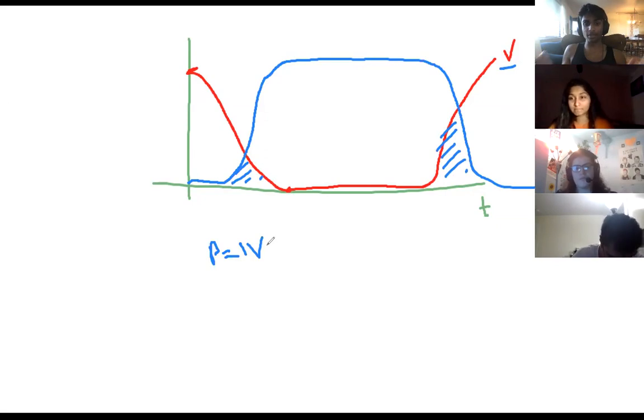So there's never that transient when your voltage is going up and your current is going down, or current's going up and voltage is going down. But in a switch mode power supply, this is something that people are very wary of. So in a switch mode, you have to worry about conduction losses and switching losses, whereas in a linear power supply, you only have to worry about the conduction losses.